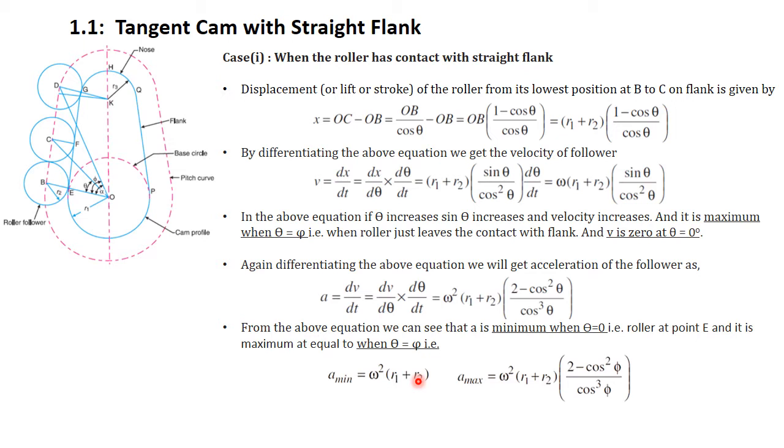In this way we can find the displacement, velocity and acceleration of the follower at any angle θ between 0 and φ on the surface of the flank of the cam, right? So here we have analyzed the follower motion on the surface of the straight flank.